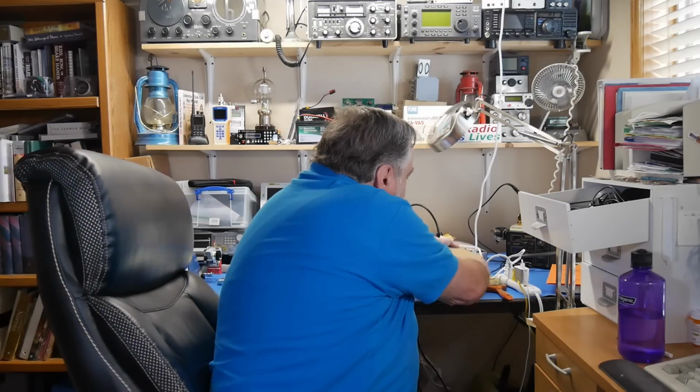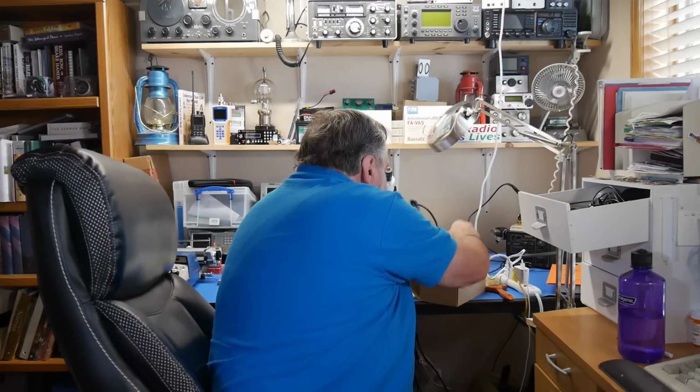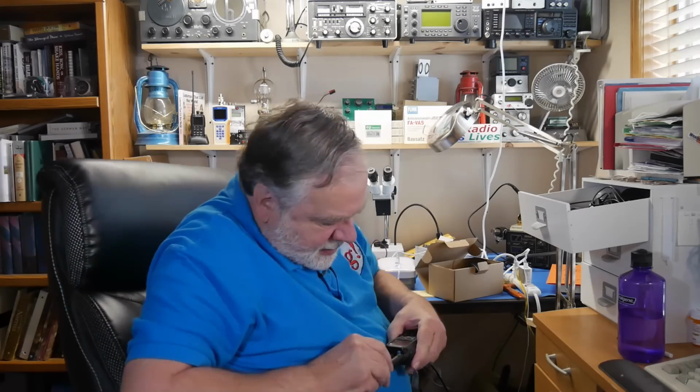So I'm going to take this new Radiodity radio, put the antenna on, and I'm going to hold this about 1.7 feet away. Okay? This is where it needs to be operated. If you're any closer than this, you have a radiation, RF radiation hazard to your brain, eyes, upper body, and so on. Okay? Now, does anybody operate their handheld like this?